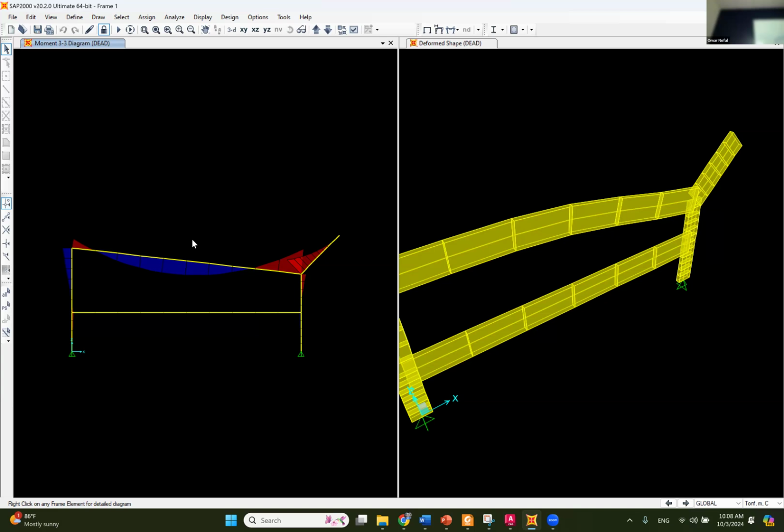For example, if you have a slab like this and there's a column here and a column here and a column there, okay? So the thing is, if you solve this slab and you make it like 4 elements, and you try to get the bending moment, the software is gonna calculate the bending moment at these points and average in the middle, okay? It calculates at the points that you define. The more that you divide, the more accurate it's going to be.